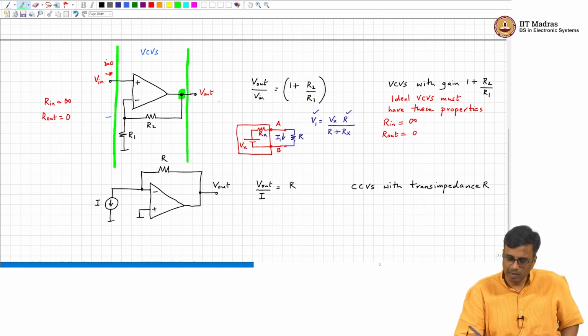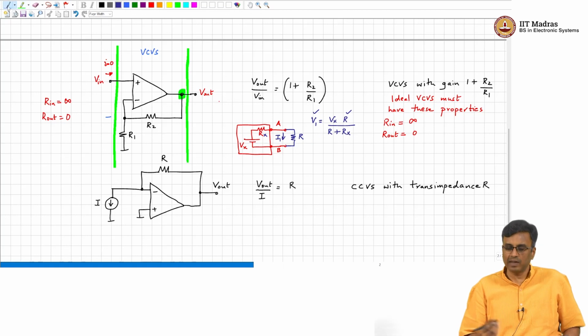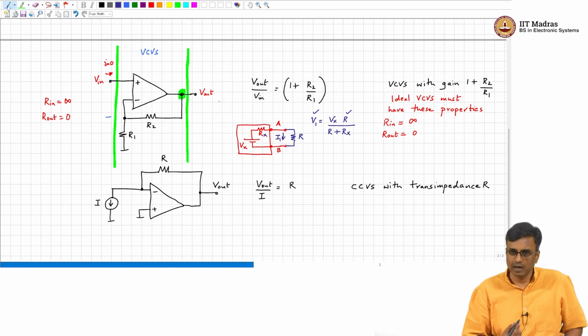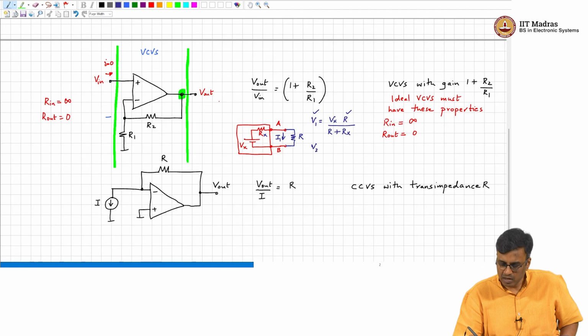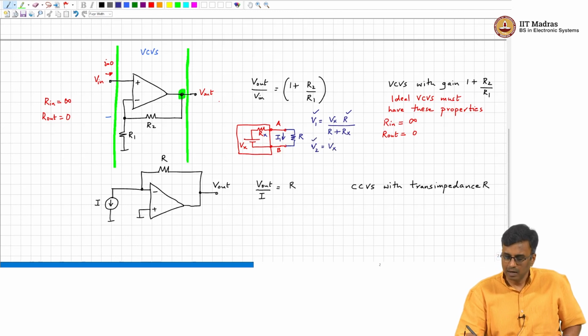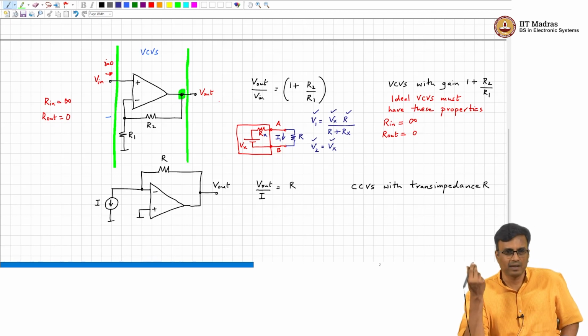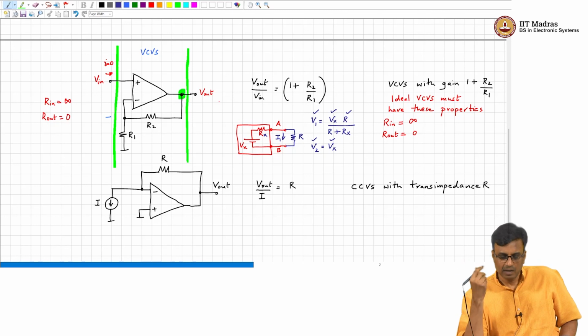The first thing is basically, without any resistor is equivalent to saying use R equal to infinity, correct. So, the open circuit voltage is simply Vx, and so once you know Vx here, then you will be able to find Rx, correct.